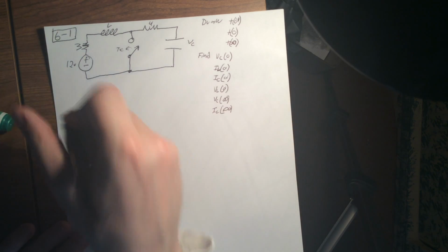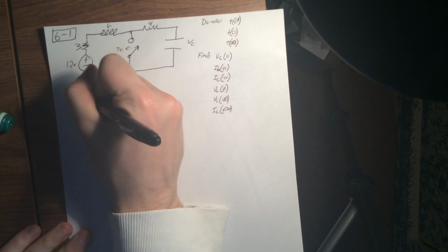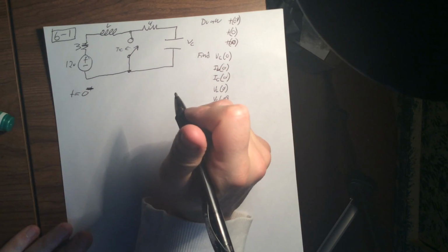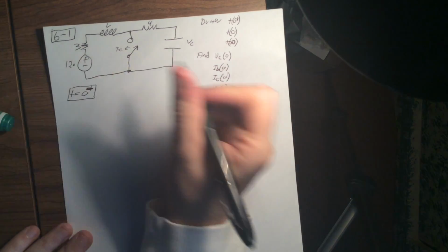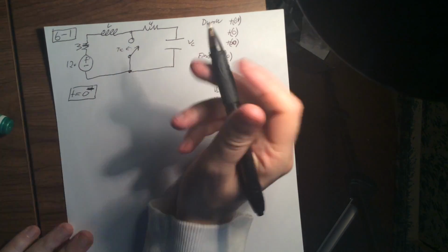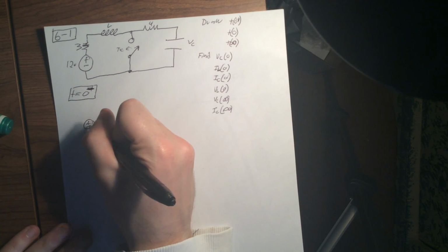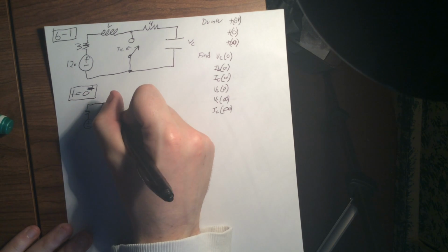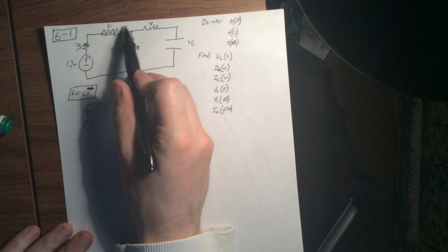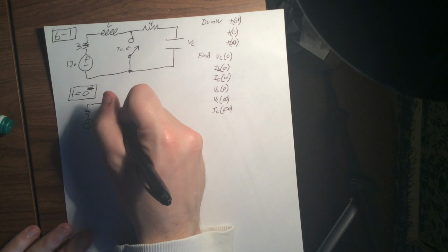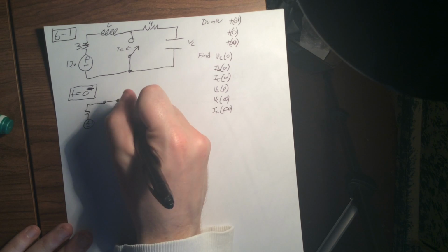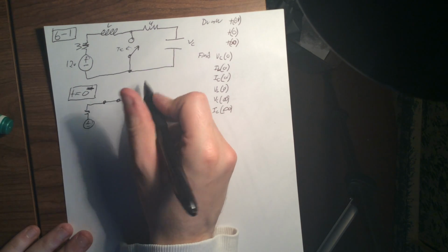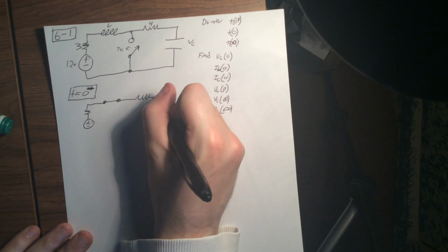So let's start at t equals 0 from the minus side, from the negative side. That's our first one, so this is going to be all the way up to 0. Let's just look at what happens. We have this. Our resistors are always going to stay the same. Our inductor, after a long period of time, is just going to be a wire again. So we have our inductor, but it's just a wire. And then we're going to have nothing coming down because it doesn't exist. It's an open hole.